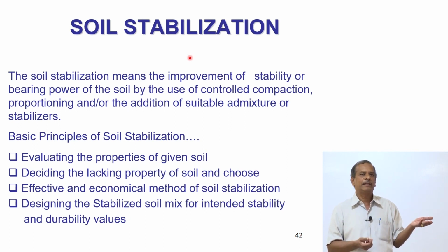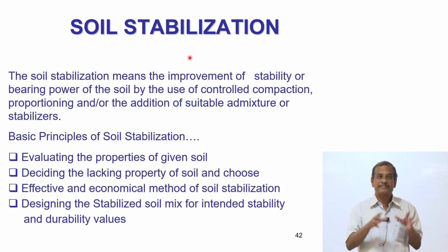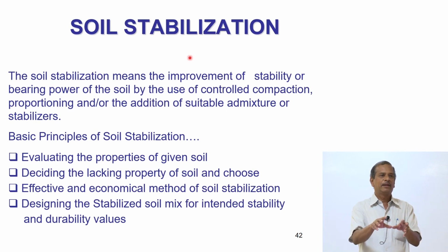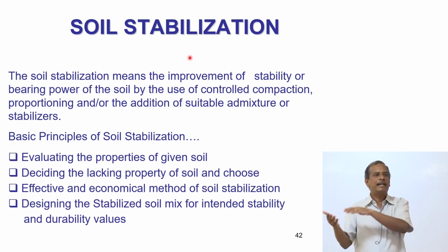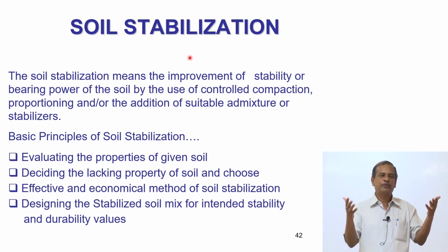Many stabilizers are available in the market today. I can get whatever strength that you need. So, you can design the stabilized soil mix. Again, the job of a civil engineer is to design a stabilized mix, find its properties, use that material property to design the thickness of the layers, predict the performance and then work out the life cycle cost. That is a challenge before you.